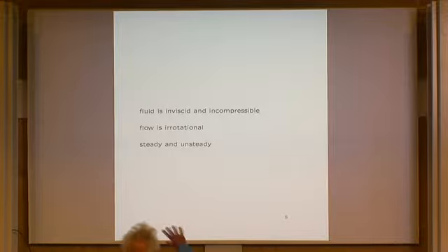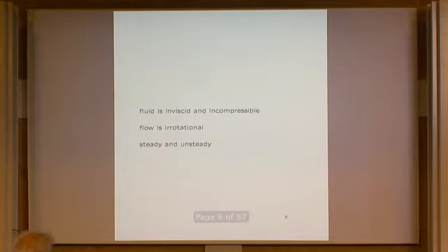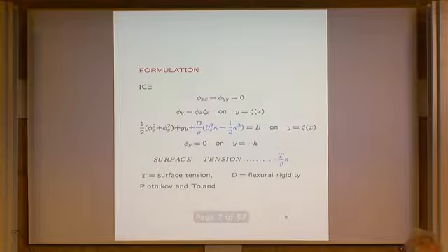Of course, the water will be assumed to be incompressible. We'll have irrotational flow. And in the talk, we're going to neglect the effect of viscosity. A lot of these waves that we're going to study will be studied in a frame of reference moving with the wave, and in such a case we have a steady flow. But we will mention, as time permits at the end, some unsteady calculations to discuss a little bit the stability of these waves. Next, something we've seen many times over the last 2 days, the basic equations.